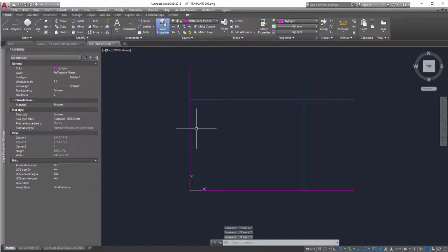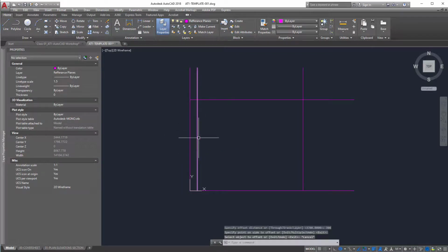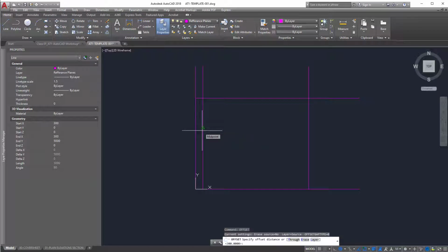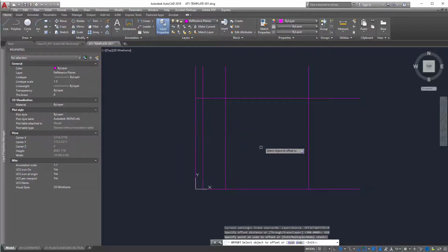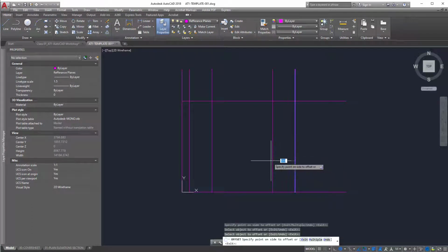So again, let's go from here. We'll start on the left-hand side of the wall, and I'll offset at 300. Notice that I don't care how long these lines are or that they're going through the whole drawing. It doesn't matter. We'll delete these in the not too distant future. I'll take this line, and now let's offset this 920, because remember it's 820 for the door leaf plus 50 mil sections for the frame. Hit enter. That's done. And again, let's click on this line while the command's still active, and type in 1,000. Hit enter.